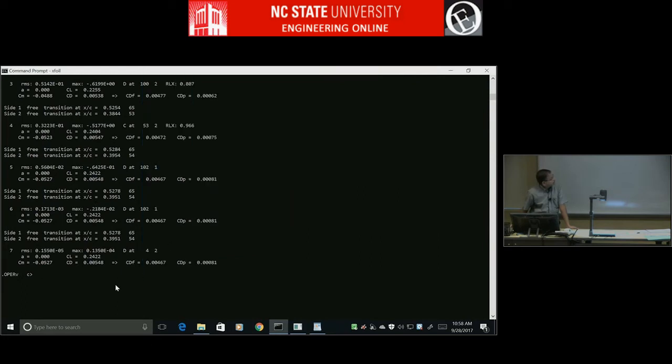Okay, so that's how you run an angle of attack. Now, I mentioned that you can also run a lift coefficient, right? The problem when you run a lift coefficient is, for small angles of attack, it'll probably work well, but it's doing an iteration between viscous and inviscid, right?